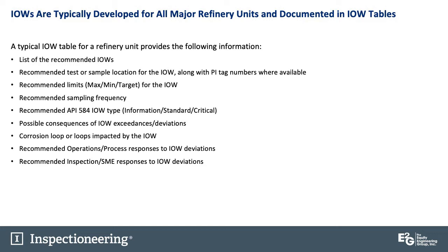Some recommended operations process responses to IOW deviations. It's pretty much impossible to cover all the possible responses, but you can cover the typical or most common responses in this IOW table, and that's what should be done. And similar for their recommended inspection or mechanical integrity subject matter expert responses to IOW deviations.